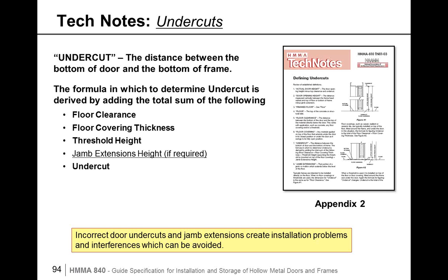Undercuts are critical in installation. There is a technical note that covers the correct method of ordering, understanding, and communicating undercuts, because this does become a problem, and you don't realize this until the door is being installed or the hardware and threshold are being installed. So this is a key tip on how to avoid those types of back charges and how to order the correct product.